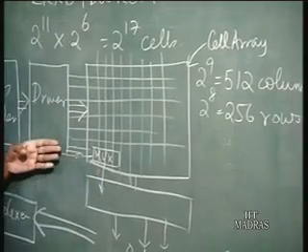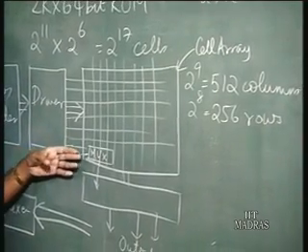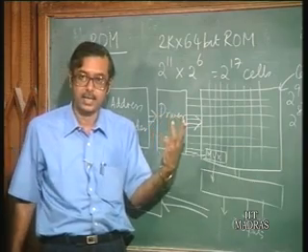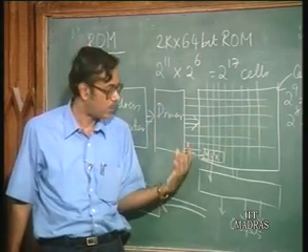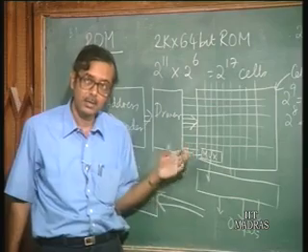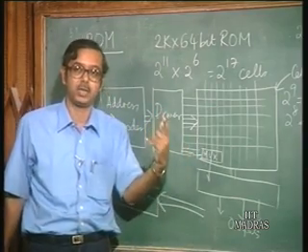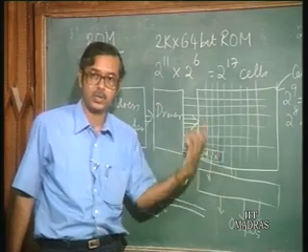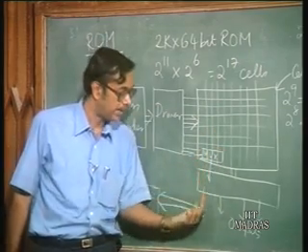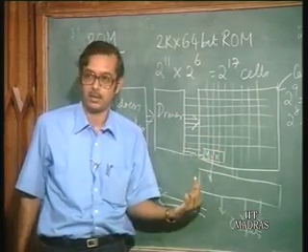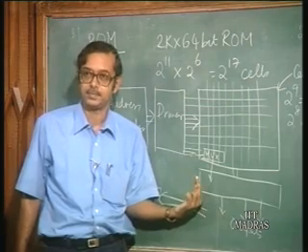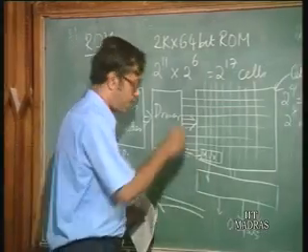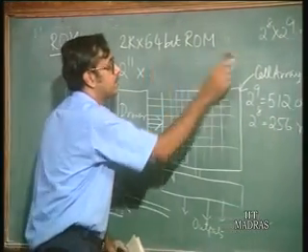There is another decoder, a 3 into 8 decoder, which uses the remaining 3 address lines, and one of the 8 output lines of that decoder is high. So, it chooses one of 8 columns. So, you have 64 into 8 columns, and at a time you choose basically one column. So, there are 64 output lines. Okay, fine, that is clear now.